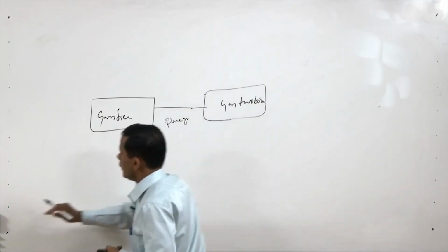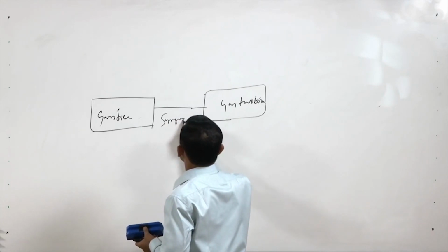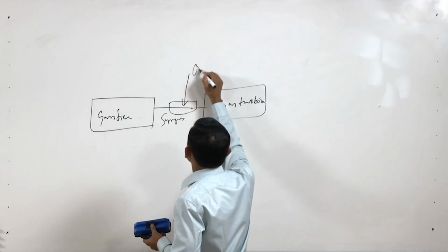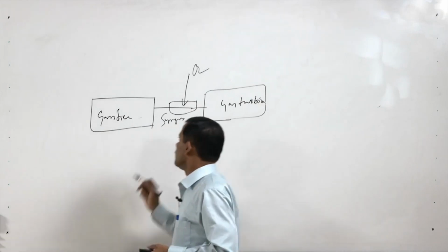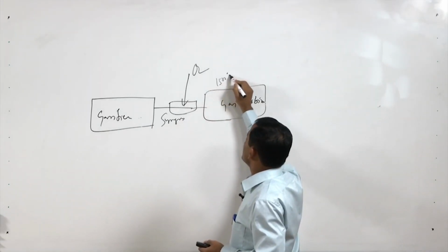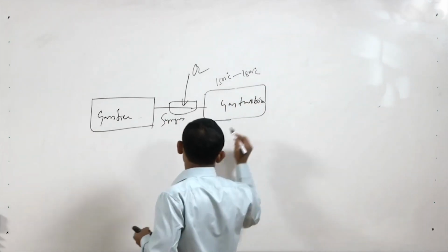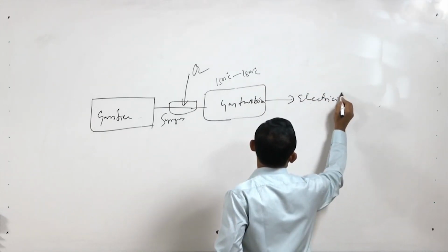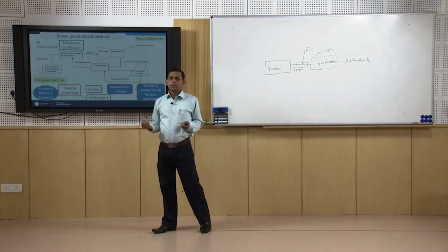Before that it will give a syngas. So, that syngas will be reacted somewhere with the oxygen. So, high temperature and pressure will be generated. Here the temperature is around say 150 degree centigrade to 1800 degree centigrade. So, that gas turbine will give us electricity. So, these are the flow sheets for the production of electricity in the power plant.